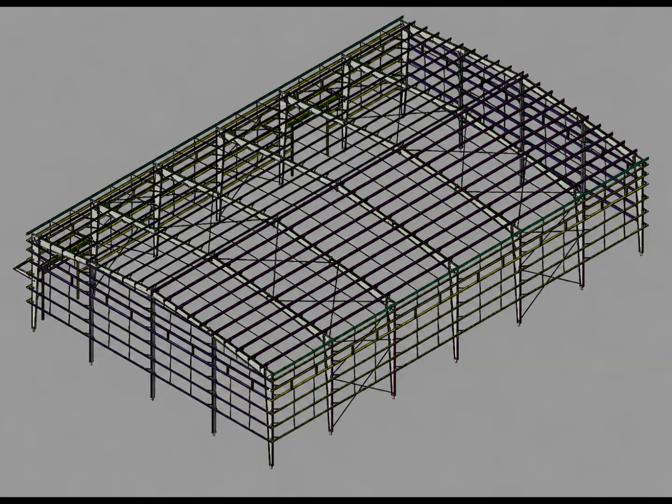Similarly, a girt must be at the correct level and connected to the appropriate column locations. A purlin must follow the correct roof slope and connect properly to the rafter system. Bracing must connect between the intended structural locations. This is why 3D modeling is not simply about making a building look realistic. It is about coordinating the actual structural members.